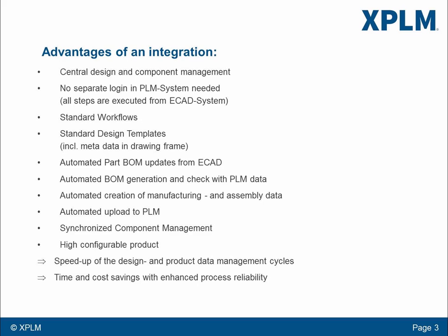The advantage of the usage of design templates will be explained more deeply later on. Workflows are automated. For example, the generation of the bill of materials, a consistency check of it with the data in PLM, the generation of the PCB and pick-and-place information, and the transfer of those data to the PLM system are included. Also, the synchronization of the component information between the development library and the product lifecycle management system is a very important issue. Within that, not only misunderstandings or double work can be avoided, but also a real process stabilization is reached. Integrate can be individually adapted to your company needs.